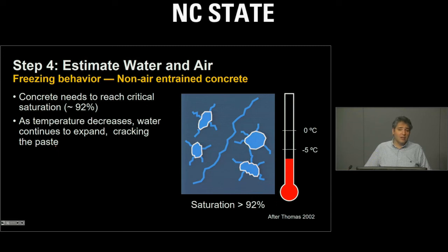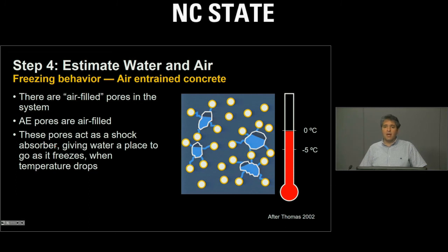Now, we all know that the concrete material does not have a very high tensile strength, and this formation of ice will start to produce tensile stresses inside the concrete and will cause cracking. Now, what happens if we have air inside the concrete? If we have air inside the concrete, and these air voids are air-filled pores inside the system, we see that when the temperature drops down, these air voids will in fact work as a shock absorber. The water will move inside them and form ice inside them, but there is enough space for the ice to form, so it will not produce tensile stresses inside the system.